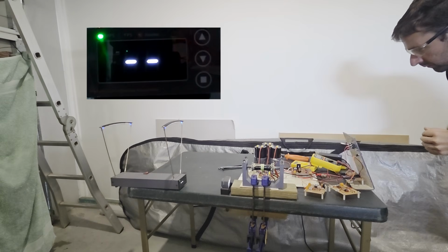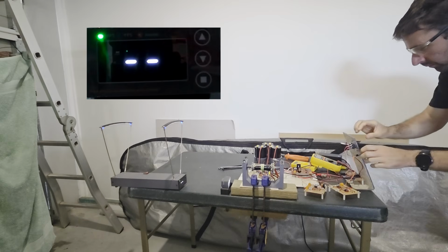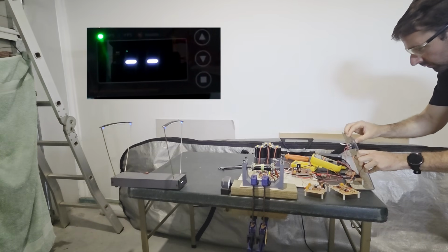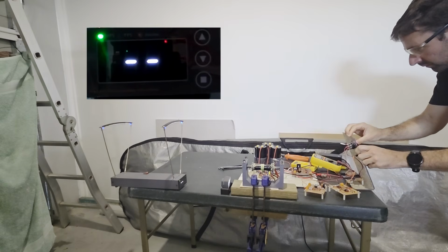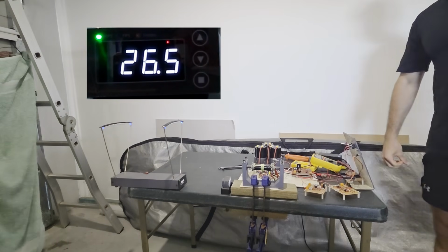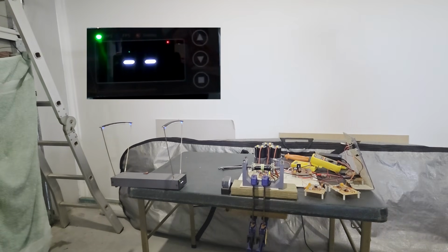Now to the coil with the same number of layers and turns, but with the wire diameter increased to 1 millimeter. We would assume an increase in velocity as we are increasing the current while keeping the same number of turns. With this arrangement, we measured the velocity at 26.5 meters a second, which is an increase of 4.3% and was in line with our initial assumption.